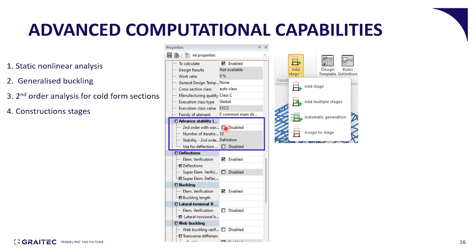The construction phases can also be automatic. So depending on the levels of organization, how you have created your structure tree, if the user has enabled the levels, the construction phases can be automated, and basically each level, each story of a multi-story building will be considered as constructed in a different stage compared to the previous ones or the later ones.